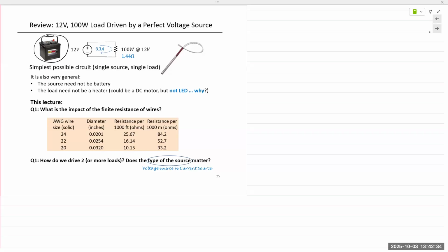Anytime we buy an appliance, let's say a space heater, right? If I bring a radiator style electric heater and plug it into the wall, the manufacturer has ensured that the cable it uses is typically very short. One of the reasons it's very, very short is because that electric heater is going to pull a lot of current, a lot of power from the power outlet. When you're pulling a lot of power, the voltage is the same, but it's going to pull a lot more current. The higher the current that passes through that wire, the hotter it's going to get.